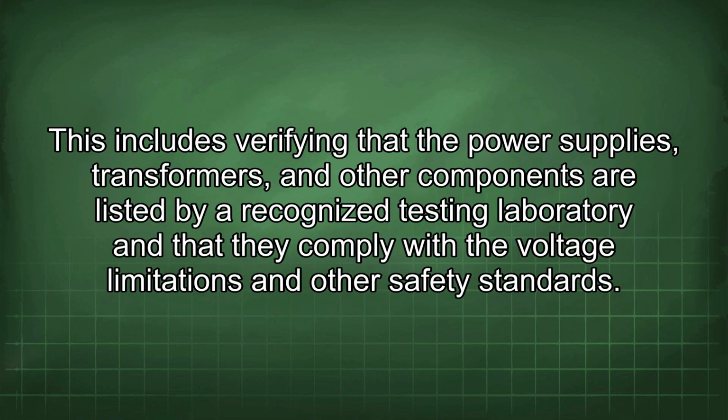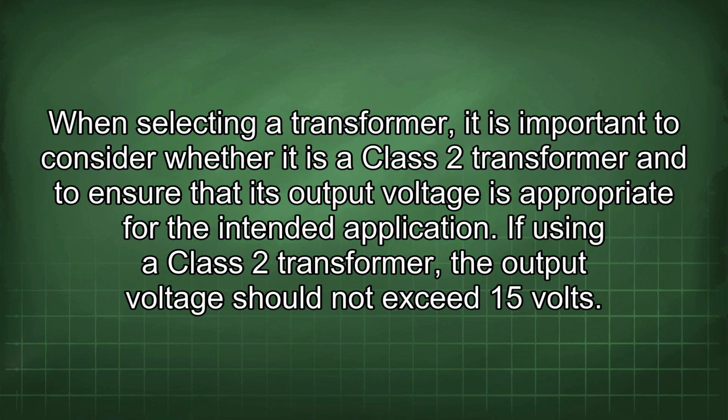This includes verifying that the power supplies, transformers, and other components are listed by a recognized testing laboratory and that they comply with the voltage limitations and other safety standards. When selecting a transformer, it is important to consider whether it is a Class 2 transformer and to ensure that its output voltage is appropriate for the intended application.